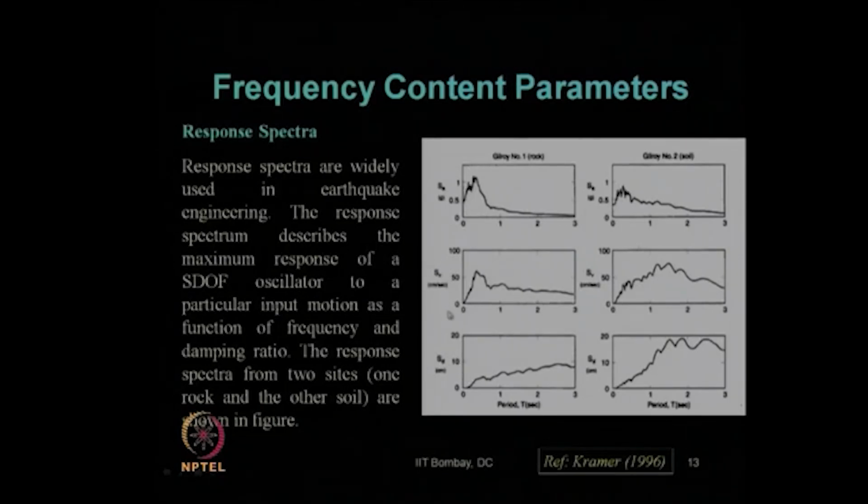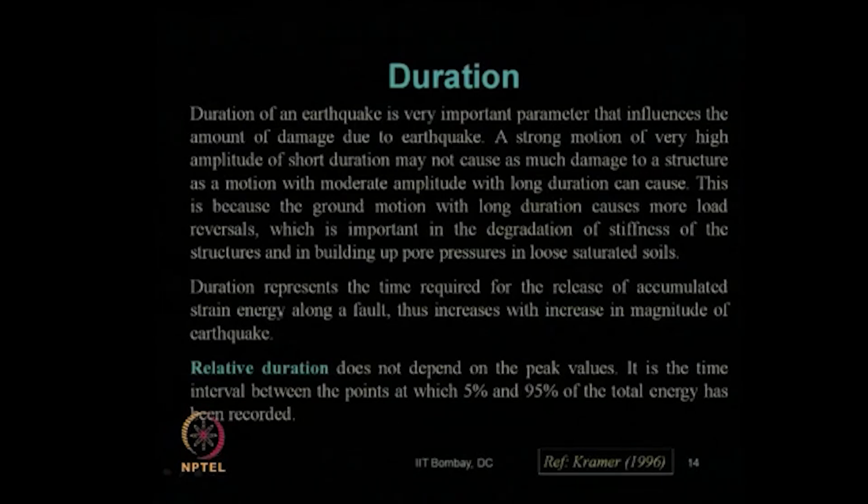How is this response spectra obtained? Through the single degree of freedom mass spring dashpot model, by applying a particular input motion corresponding to a particular exciting frequency and the damping ratio. So, we will derive it today in this lecture.